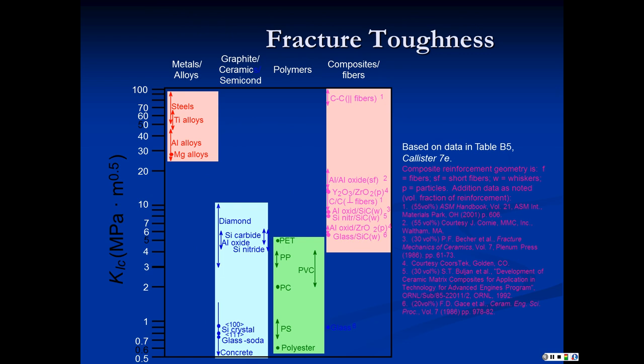So what do fracture toughness values look like? Well, here's on an absolute scale right out of your text. Metals are here, ceramics are down here, polymers are down here, and then composites, and these are all ceramic composites actually, look pretty good, possibilities of pretty high toughness. This is log scale, right? So there's a lot of compression here, and so it's a little deceiving in that regard.